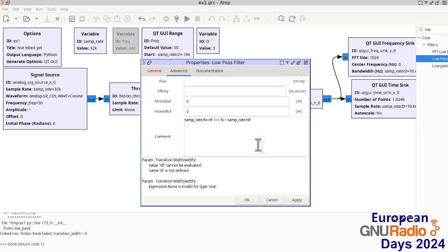Now, another way of saying that the convolution theorem transposes time domain and frequency domain weighted filtering is to consider that a filter that outputs samples y[n] is a weighted sum of taps b[k] multiplied by the weighted past quantities x[n minus k].